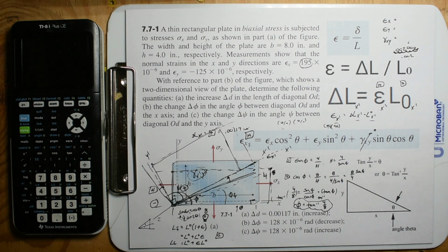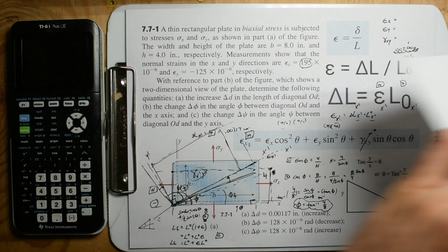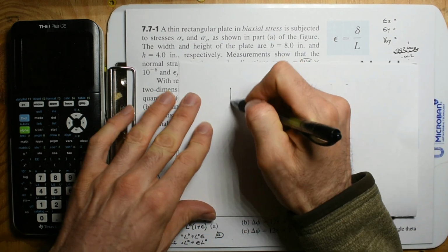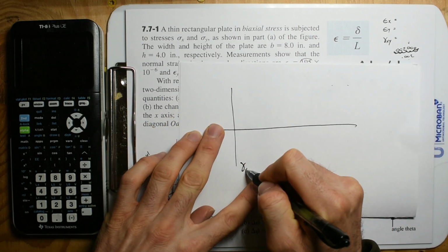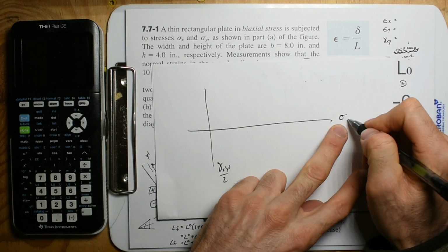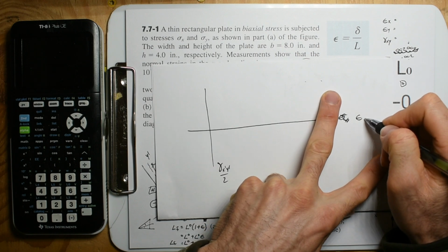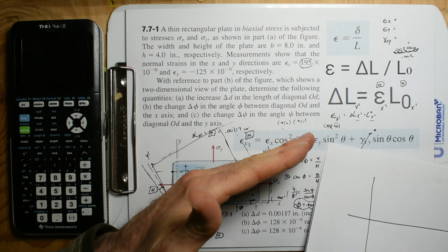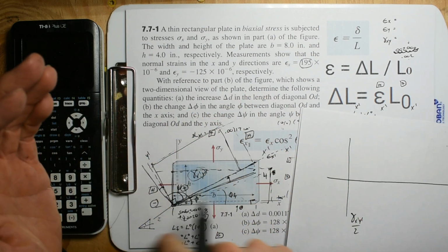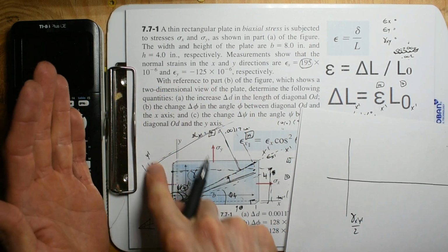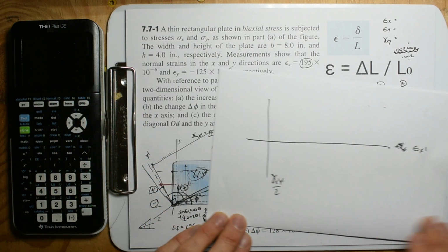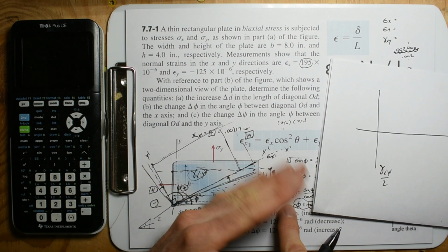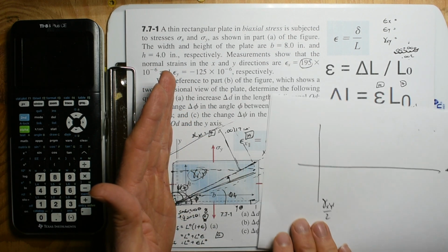Hell yeah. And these problems are the introductory step to learning about the full equation. With the Mohr circle, you have this x1y1 divided by 2, and this strain in that x prime direction. Now this x prime direction can be rotated 360. So I can just rotate it an extra 90 to get the strain in that direction. And so I could rotate it none and get the strain in the x. Cool. And then I could rotate it 90 and get the strain in the y.